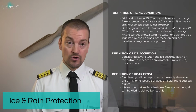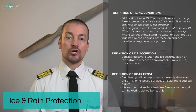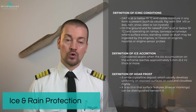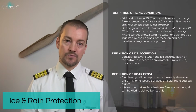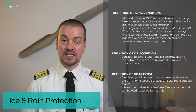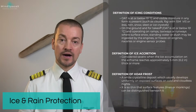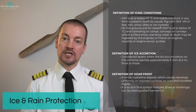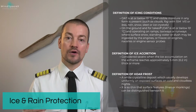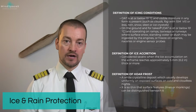And definition of frost, hoarfrost, on the upper surface of the aircraft, specifically something you experience during cold, calm nights where the temperature dropped below the dew point with freezing surfaces and a lot of moisture in the air. You will find a white crystalline deposit which usually develops uniformly on exposed surfaces in cold and cloudless nights, and that's the upper surface of an aircraft.